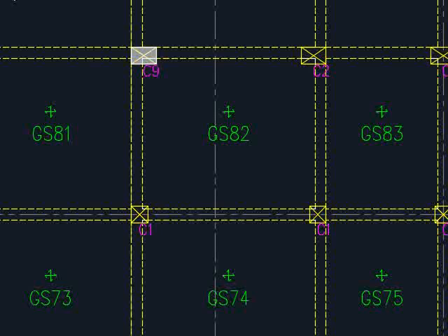Then you observe the amount of reinforcement bar, as well as the shape of the columns in terms of size and dimensions, and make the necessary classifications so that amounts of reinforcement bar which are close are rounded up, so that you have the chance to provide additional reinforcement bar instead of reducing the amount of reinforcement bar.